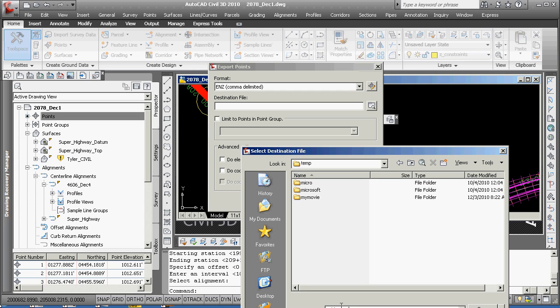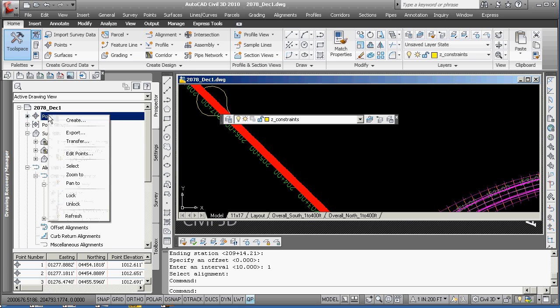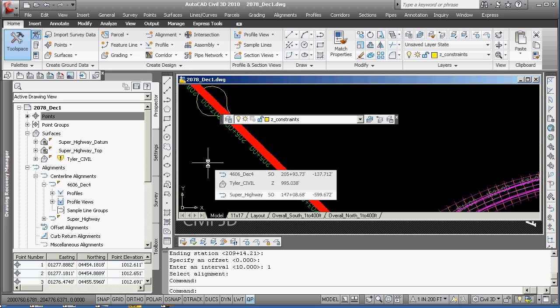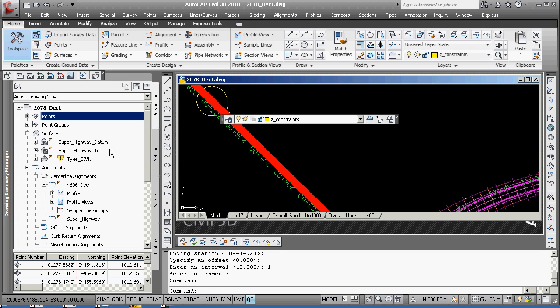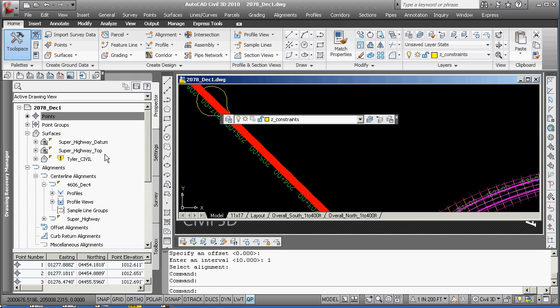So as soon as you have your vertical, you can go ahead and put that stuff out. Cul-de-sac points, hit open there, and then you hit OK. It sends out all your points, and then you can go points, select, and then you'll be able to delete them. I might suggest that a good thing to do for this point generation is to save your drawing, do the point stuff, and then just quit out. That's perhaps just me, but I'm going to go ahead and edit points. All right, see how this goes, and exit out.